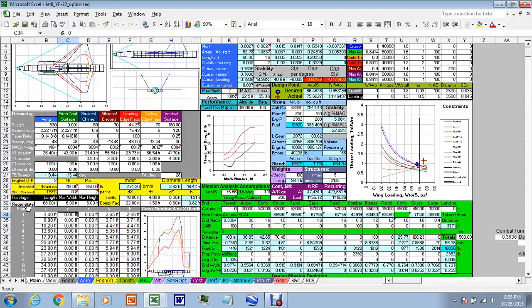You see it's making the airplane into an ogive cylinder fuselage, and that dramatically cut down the fuel burn, and the smaller fuselage also weighs less, so we have quite a bit of extra gas. We've got 3,000 pounds of extra gas. But the area ruling doesn't look real good. There's this great big bump back here, so since we made a cylinder in the rear part of the airplane instead of that nicely tapered fuselage, let's go get that tapered fuselage and put that back. We still like the way the fuselage tapers in the vertical.